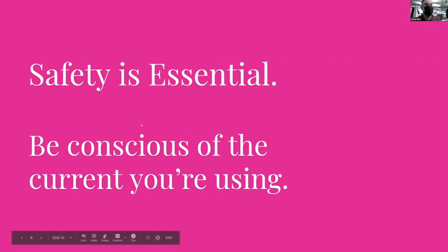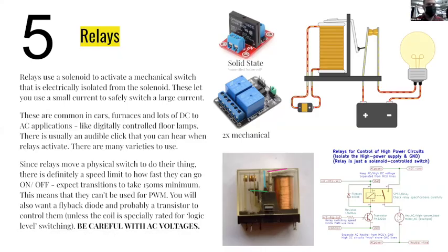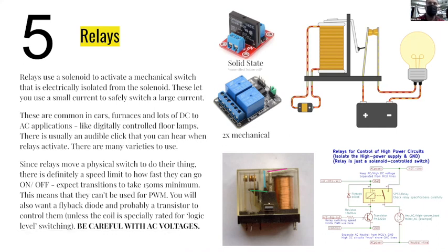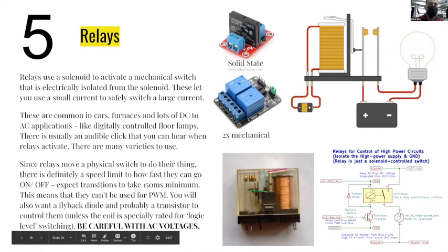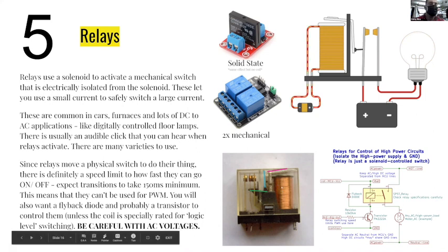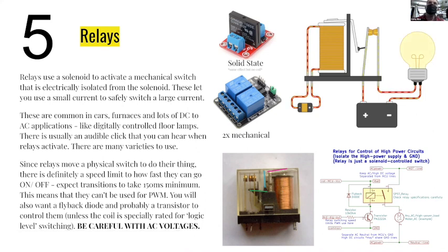That said, we're going to talk about relays, which don't do any of that. It's a perfectly safe way to handle switching of mains voltage with an Arduino. So here are relays. You can see laid bare the coils that are in them. These are solenoids, absolutely. And basically all they are is a solenoid activated by an Arduino, in our case. But it's a solenoid that doesn't take a whole lot to make happen. But when you do that, instead of going up and hitting a xylophone tube, it flips a little switch.